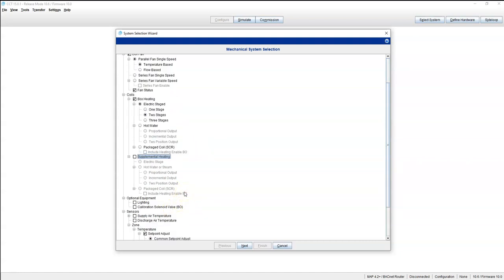If we couldn't close the damper because we're in a lab or something where we cannot stop the airflow, we would put a solenoid valve on the high side of the velocity pressure tube.